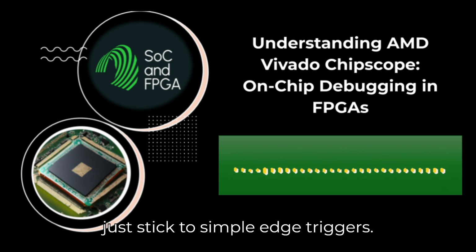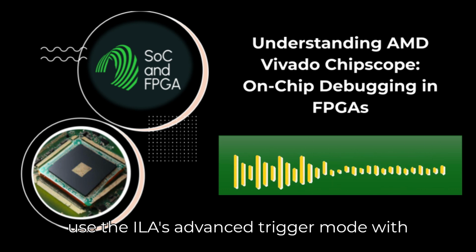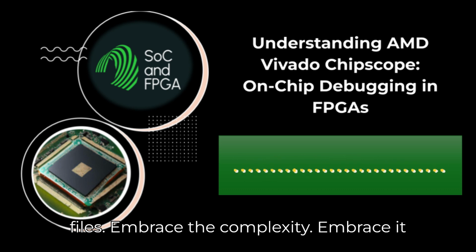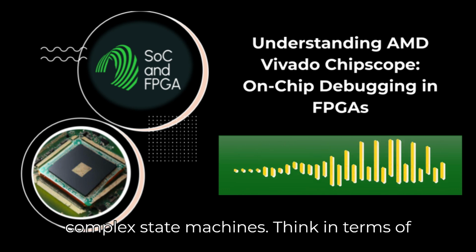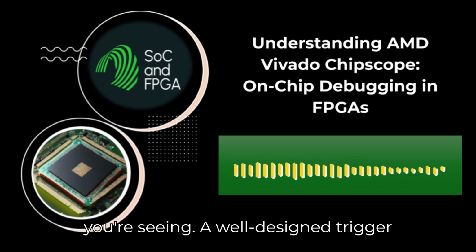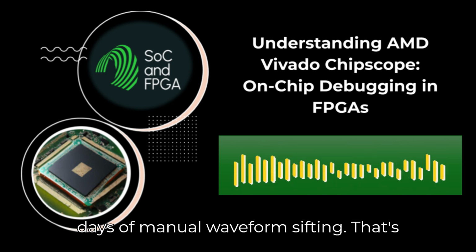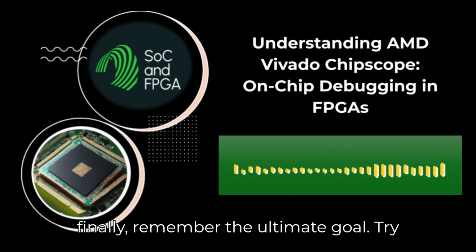Yes. Fifth, master advanced triggering. Don't just stick to simple edge triggers. Invest the time to learn and effectively use the ILA's advanced trigger mode with those custom state machines, the .tsm files. Embrace the complexity. For protocol-based bugs or issues in complex state machines, think in terms of sequences. Define the exact sequence of events that constitutes the failure you're seeing. A well-designed trigger state machine can isolate exactly that sequence, saving you potentially hours or days of manual waveform sifting. That's where the real detective work pays off. Pinpoint the problem precisely.